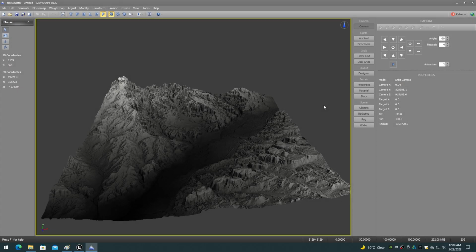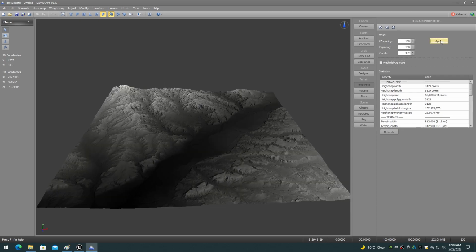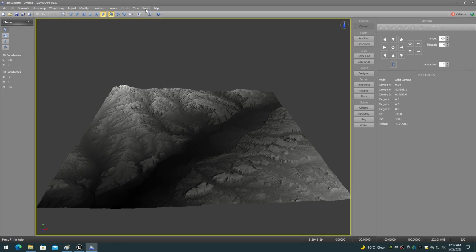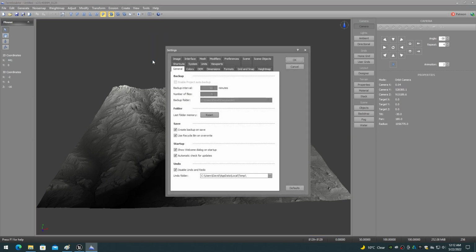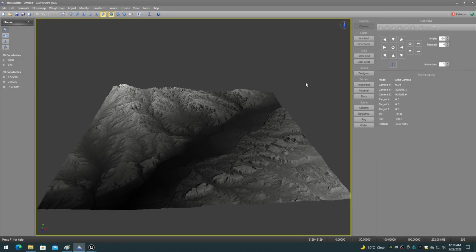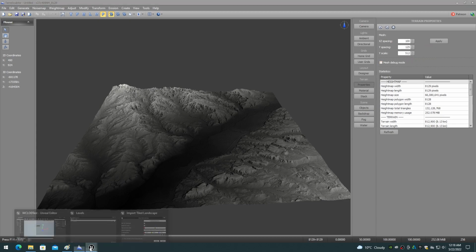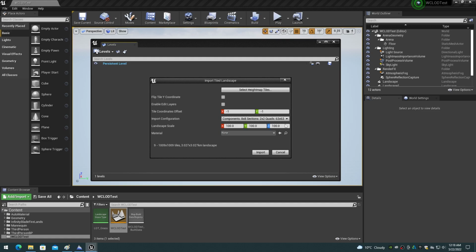So it is a good idea to use TerreSculptor to check the terrain height using the terrain scale properties to be able to choose a good scale Z for the Unreal Engine tile importer. TerreSculptor scale values can be set to match Unreal Engine so that the terrain in the viewport matches its size in all dimensions. This way you can transfer the TerreSculptor spacing Y value over to the Unreal Editor landscape scale Z value on the import dialog to correctly scale the landscape in Unreal Engine.